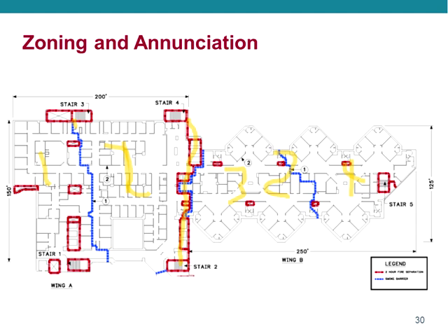So what we want is that if I have notification appliances throughout this zone over here, they must all operate at the same time. And they don't necessarily have to operate at the same time as appliances over in this zone. But the appliances in this zone must all operate together, because it doesn't make sense to partially evacuate a single zone. Now again, the way to find out where your zones are located is to go to your life safety plans for the building. They're going to be created by the architect and reviewed by the FPE, and they will show you clearly where those zones are.